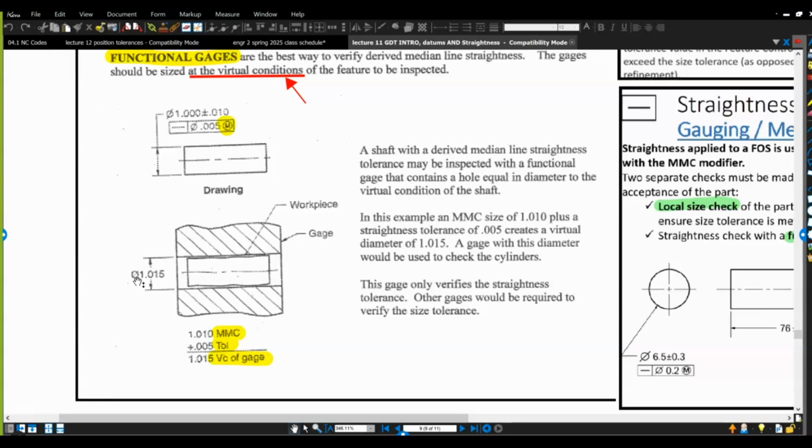The CMM is like a probe that touches the part and then creates a 3D model, pretty much. It allows you to find out if your part is on spec or not on spec. But that takes a lot of time, right? So we can combine the geometry and the dimensional imperfection into one single thing. For the pin, the biggest I can get plus the crookedest I can get, I can create a gauge, a piece of metal that is to that virtual condition, and make it. Grab my pin, whenever 100 of them, grab the first one and throw it inside of it.